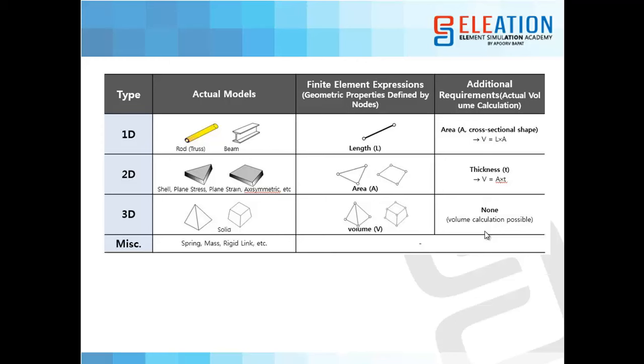So we create the elements along the area, but again we have to generate the entire volume to solve this problem. So we give thickness as an input while we do 2D meshing, after which, on providing the thickness, my software calculates the complete volume, that is area multiplied by thickness gives me the volume of that entire domain.